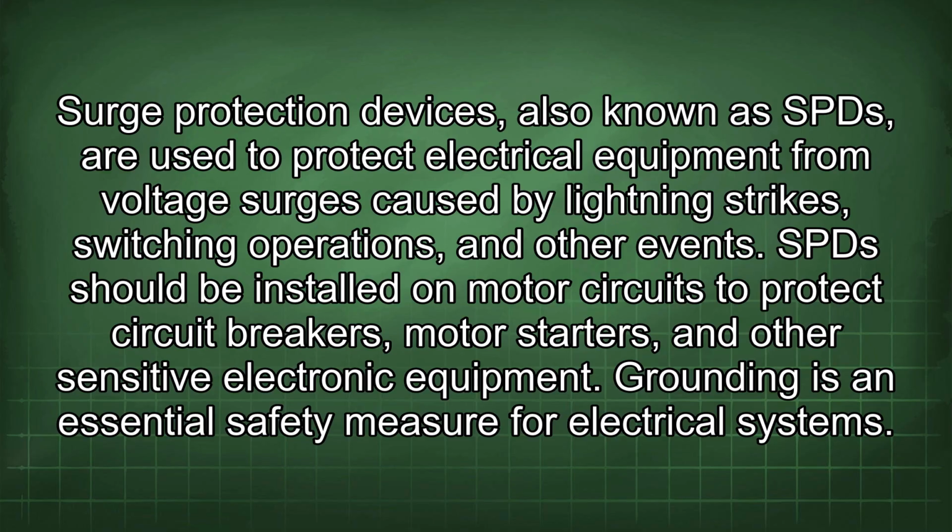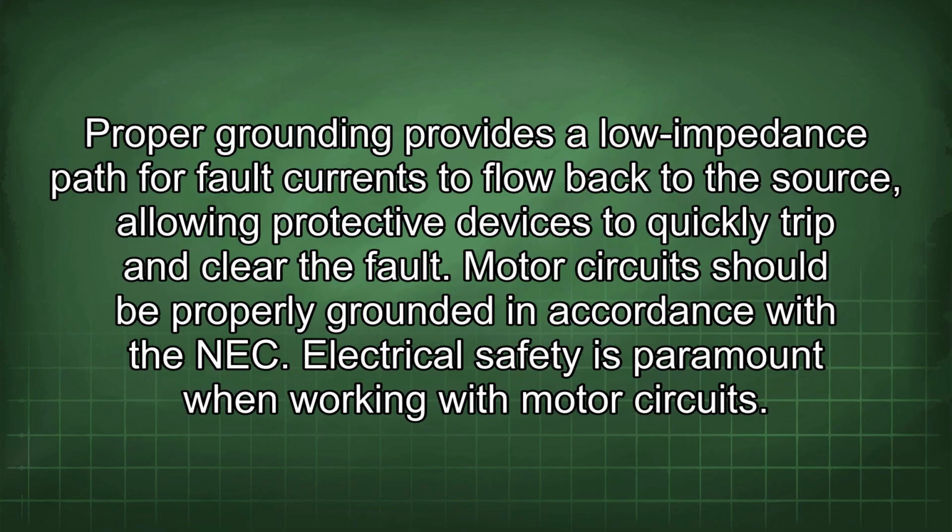Grounding is an essential safety measure for electrical systems. Proper grounding provides a low impedance path for fault currents to flow back to the source, allowing protective devices to quickly trip and clear the fault. Motor circuits should be properly grounded in accordance with the NEC.